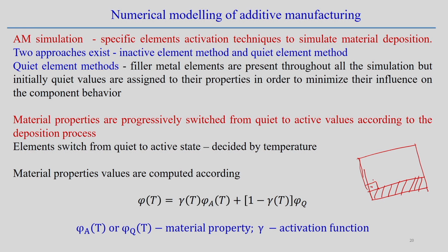So, over this, the heat source is moving in this particular direction. Next, another material deposition, another element. So, keep on activating this element, and that increases the solution domain. This is one way: once the heat source moves, keep on activating the elements.